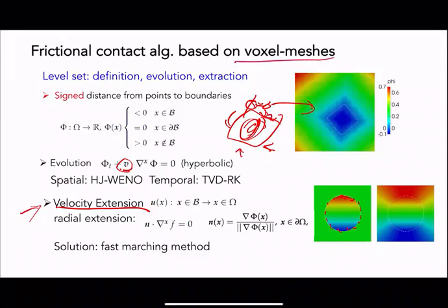This method is actually, the level set is solved on a voxel basis. In fact, in the finite volume regimes that are available on the internet, what we actually do is couple this finite volume code with a homegrown material point level set code, so that we can capture the movement and the deformation of the particle by generating the corresponding level set that represents the new boundary or the geometry information of the particle.